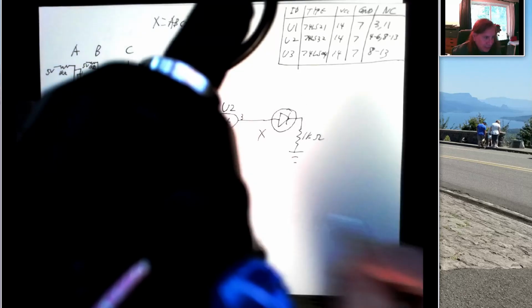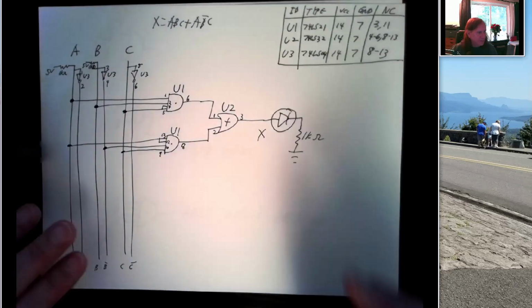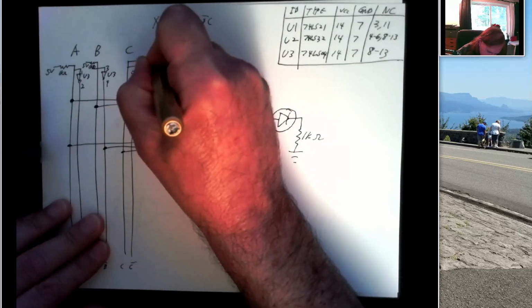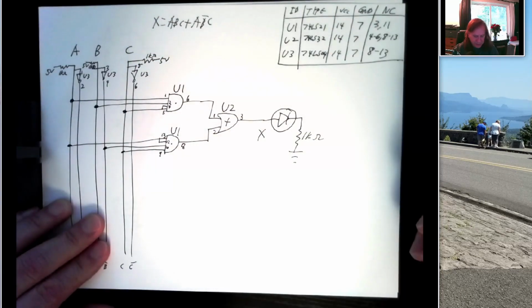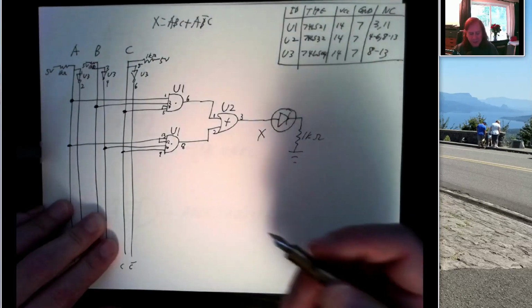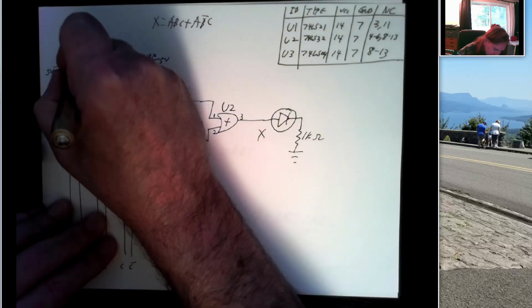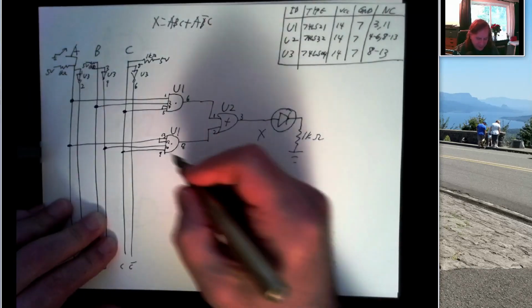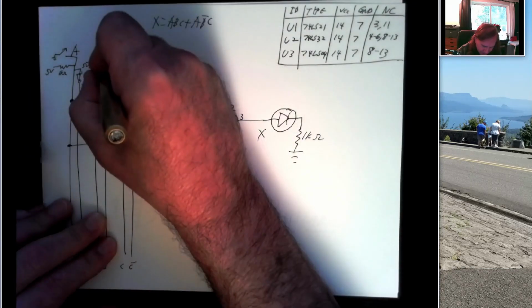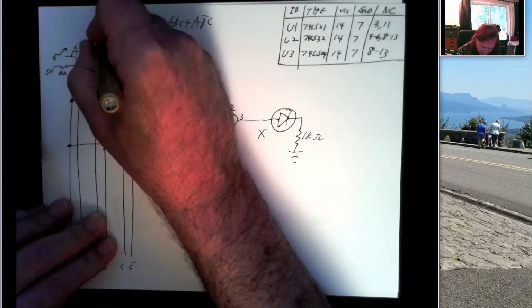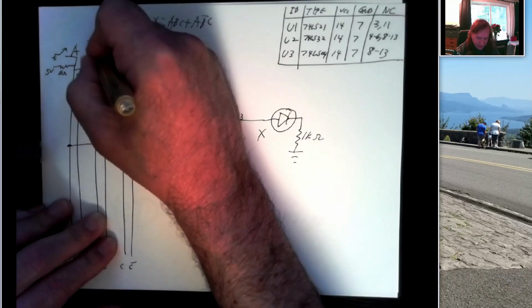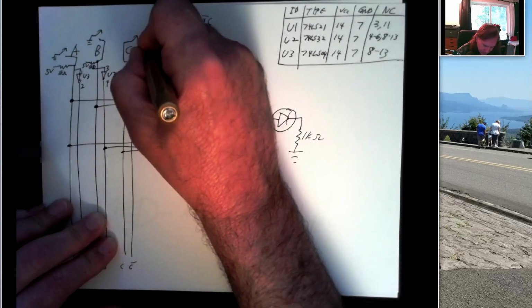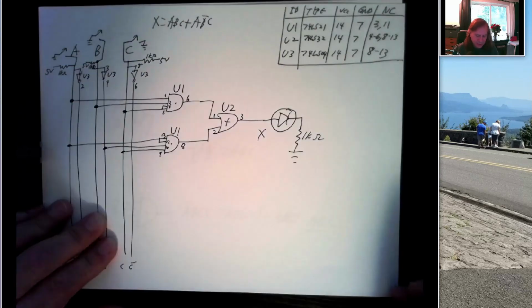And so you can see where I'd like to have used a pencil for this. And let's take C, connect that through a 1 kilo ohm to 5 volts. And then each of these inputs we're going to control with a switch. So we're going to take a switch here, connect this to ground. That's our input A. We're going to take this point, have a switch we can use to connect that to ground, and then point C, we'll have a switch to connect that to ground.